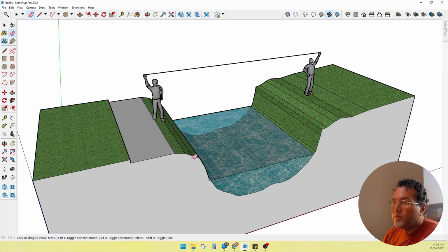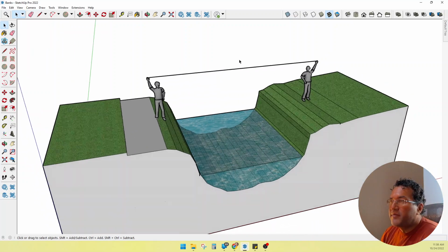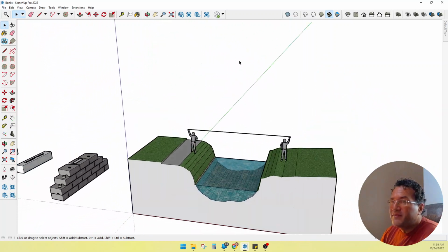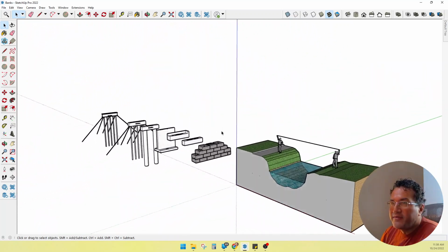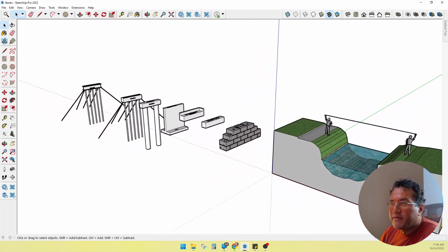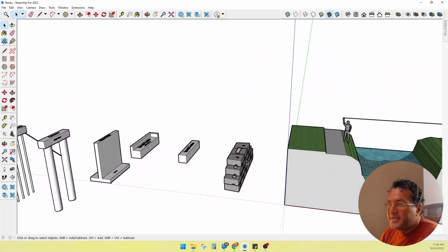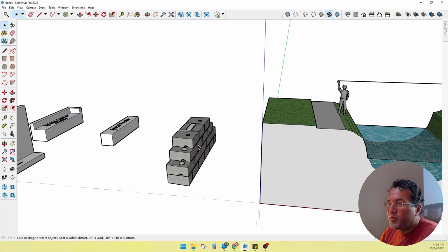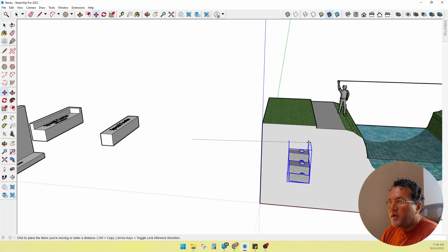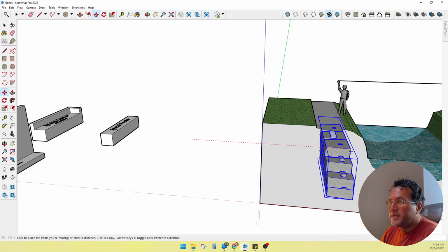Now when we go into regular traditional abutments, I'm going to list these from least expensive to most expensive. You can see these over here. So I have all these different abutments lined up for you that we're going to talk about. So the least expensive abutment option is going to be our precast. Okay, so the precast, you will dig out a hole and you'll just set these right in place.